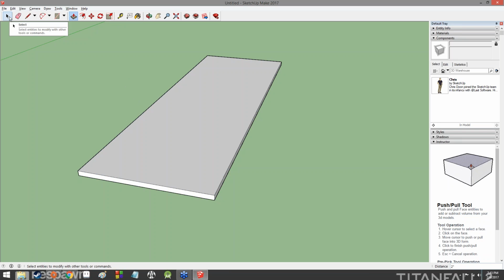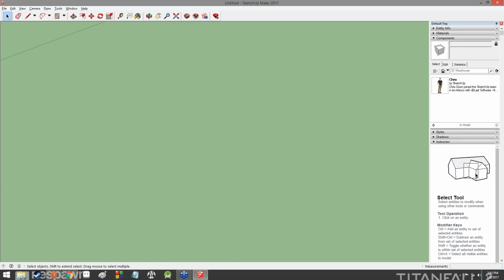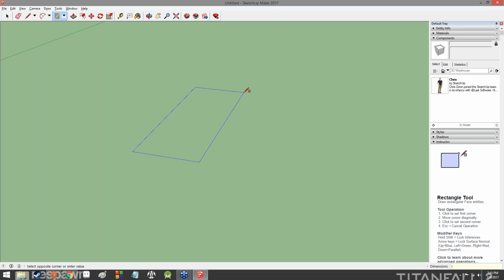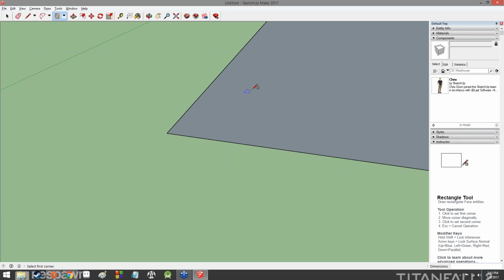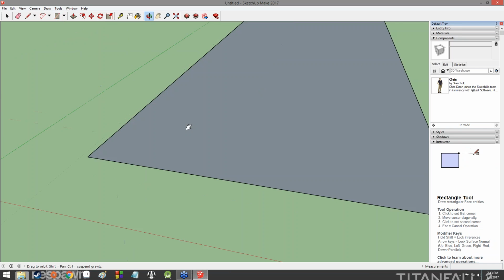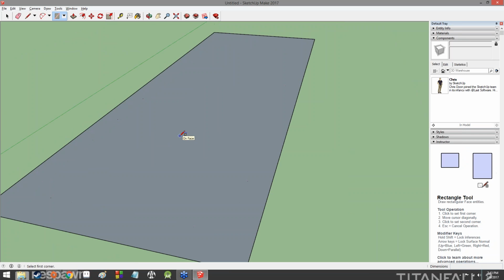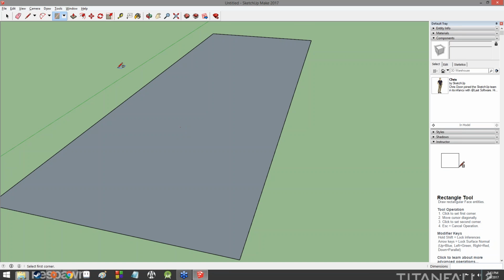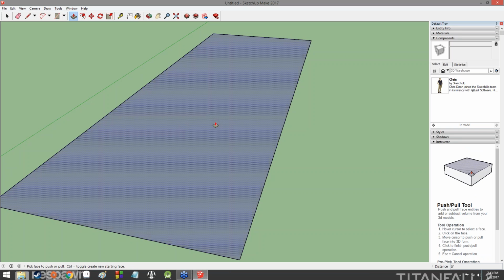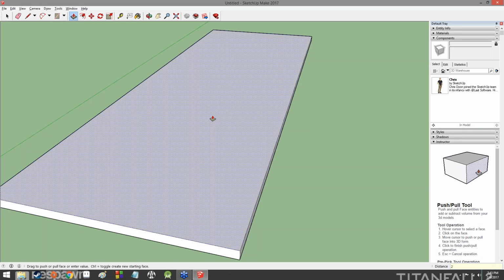Oh my gosh. 150 and then a single quote, comma, 50 and then a single quote, comma, 150 and then a single quote. You have to be careful about your units as well, because SketchUp will default to the smallest possible. When I just typed 50 and then 150, it defaulted to 50 inches and 150 inches when I wanted 50 feet and 150 feet. To fix that, just type one single quote afterwards, because that's the shorthand for foot.